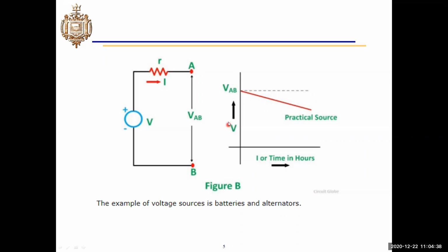That is the problem we are facing. That means in order to supply high voltages to the load, what do we have to do? We have to maintain the internal resistance of the source at a minimum. Then maximum voltage can be supplied from source to load. Am I right or not? We have to keep the internal resistance of the source minimum. Then only is the supply voltage equal to the output voltage of the source.